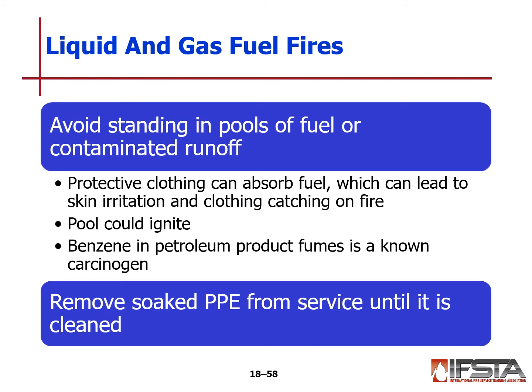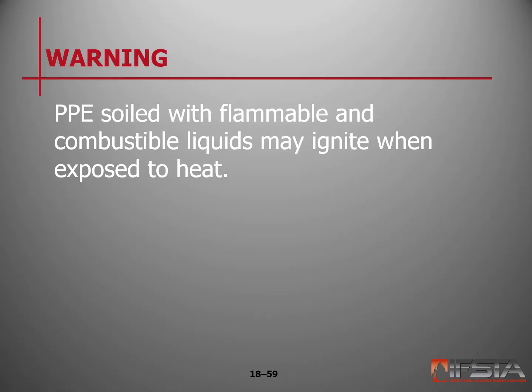Avoid standing in pools of fuel or contaminated runoff. We got to remember that protective clothing can absorb fuel, which could lead to skin irritation and your clothing actually catching on fire. The pool could ignite. Benzene in petroleum product and the fumes is a known carcinogen as well. Remove soaked PPE from service until it is cleaned. Again, a warning here, PPE that is soiled with flammable and combustible liquids may ignite when exposed to heat.